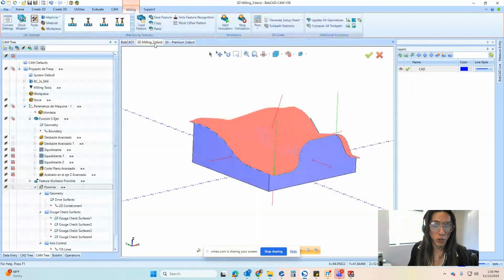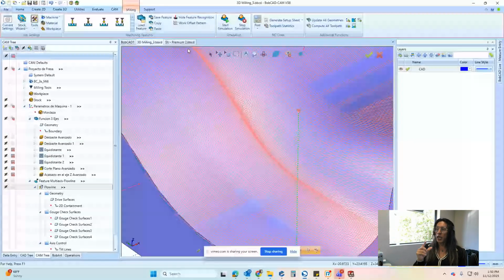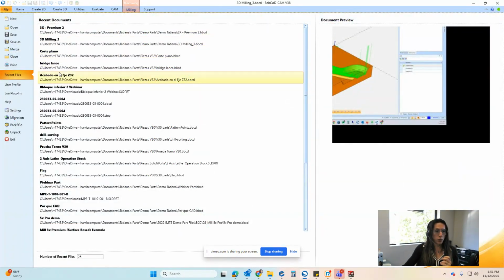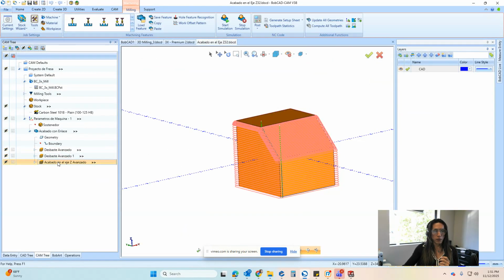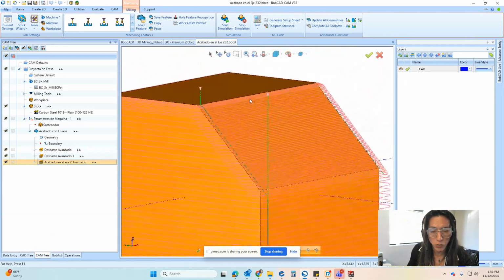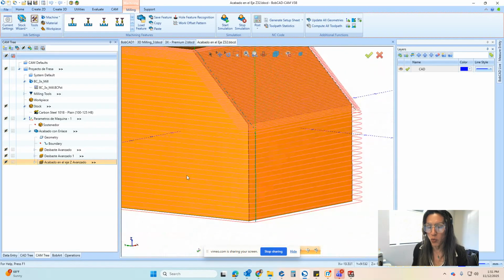We were able to see a little bit of 3D surfaces. We looked into Z-level finish and variable step over. The Z-level finish with variable step over is pretty cool because you can cut with a smaller step over only the areas you need, not everything. So I'm just going to show that once more. This is what we saw, where the finish only cuts with a smaller step over here, and then the rest is with a bigger step over.